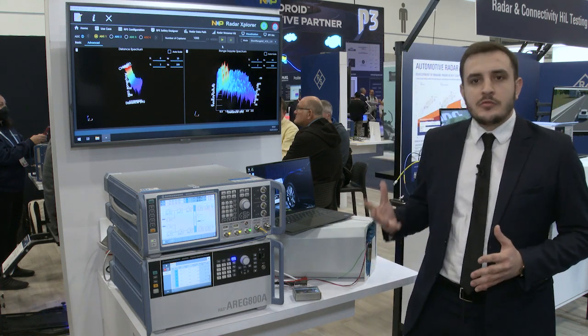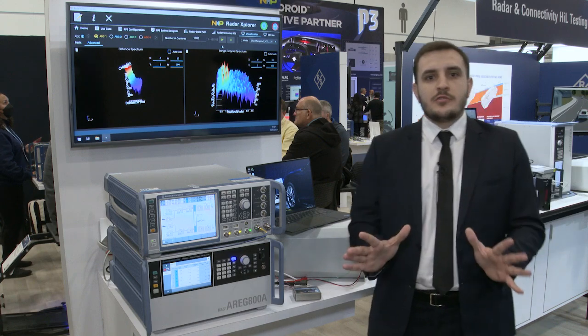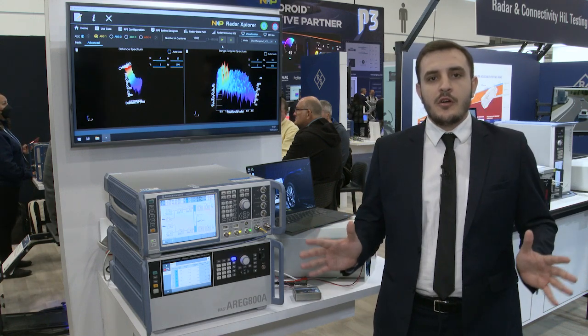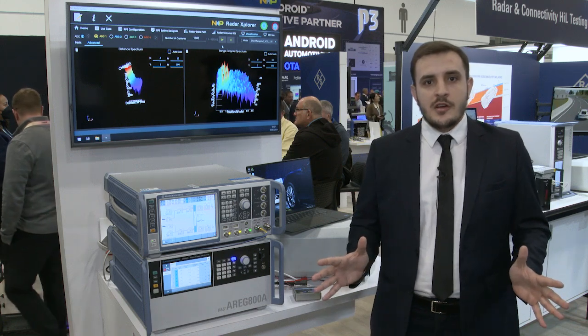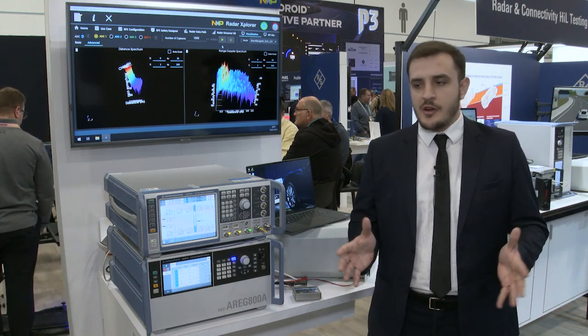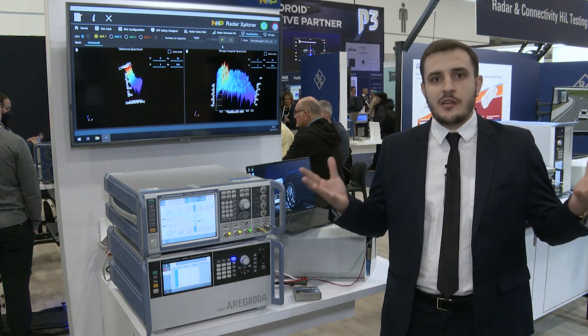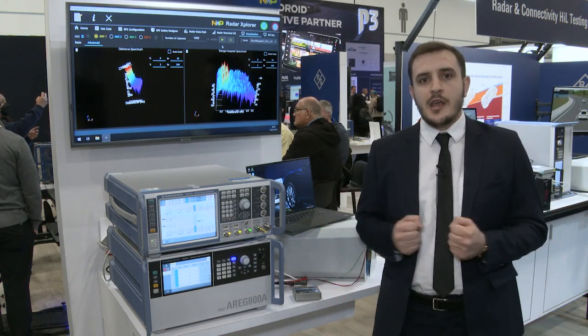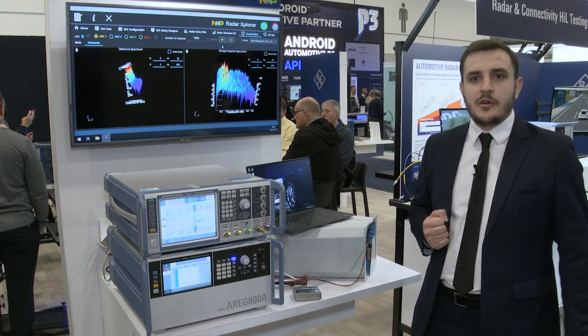because now I'm going to launch a new feature for the REG800A. It's a software feature, we call it K814 or Near Object Range for FMCW radars. This is a unique feature and it's patented by Rohde and Schwarz. And using this feature, we are now able to reduce the distance of an artificial object down to the air gap value of the radar under test, which in this configuration is 0.5 meter.